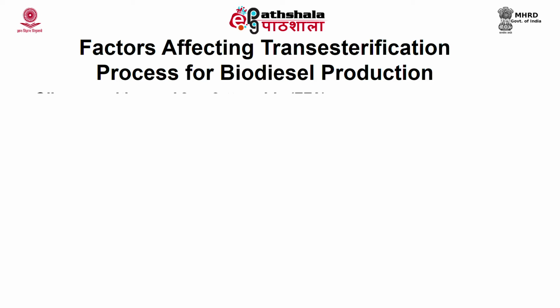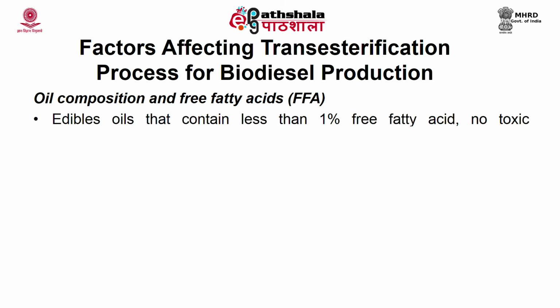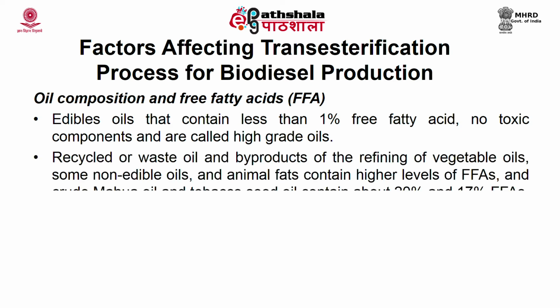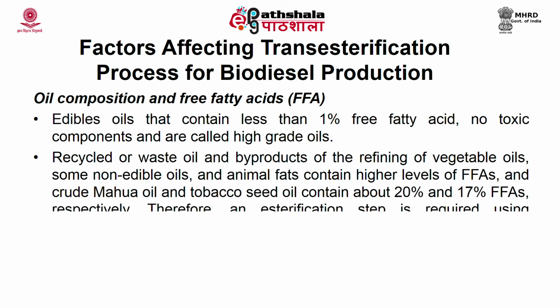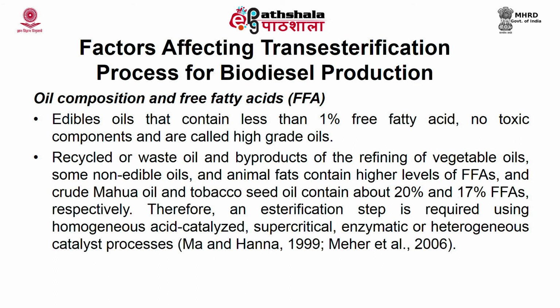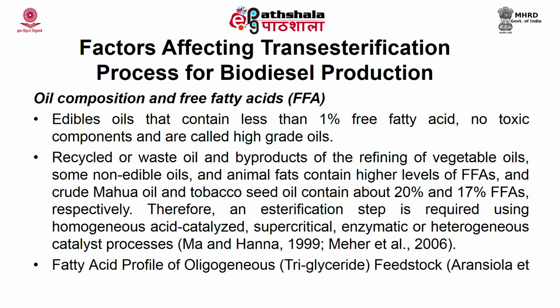The first one is the oil composition and free fatty acid content. Edible oils that contain less than 1% free fatty acid and no toxic components are called high grade oils. Recycled or waste oil, byproducts of refining vegetable oil, and some non-edible oils and animal fats contain higher levels of free fatty acids, and therefore an esterification step is required using a homogeneous acid catalyzed, supercritical, enzymatic or heterogeneous catalyst process.